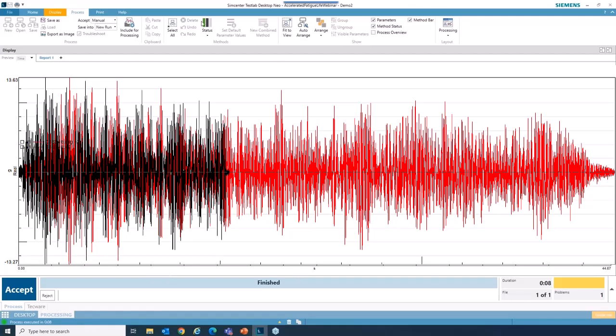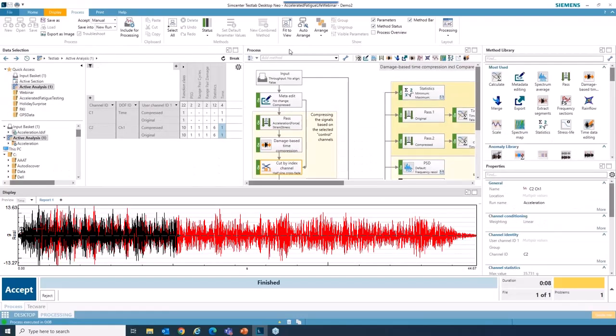Now notice the amplitudes. The maximum amplitude is about the same as the one which we saw in the original time history, and the maximum and minimum still stay the same. That is the beauty of this method, that you are not introducing unwanted behavior because of the increased loads. You're keeping the load levels the same and accelerating the test.